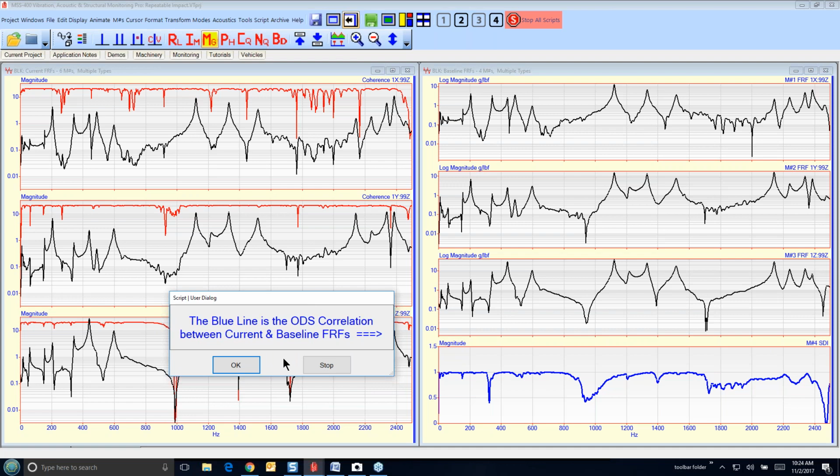for the repeatability. The other advantage of using this would be in a route-based monitoring program. If I am using magnetic sensors, accelerometers, and I place them on the machine, well, you want to ensure that when you make measurements from various points on the machine, that set of cross-spectrum data or auto-spectrum data can be used.